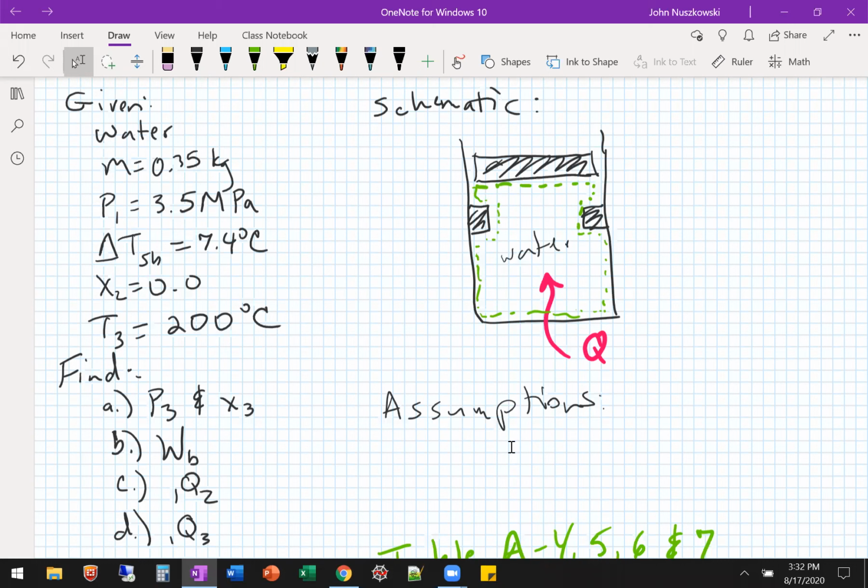So the specific volume? Not from 1 to 2, because the piston's moving down, right? So we're cooling, and the piston moves and hits the stops, state 2, right? So that means the volume will change, and if the mass is constant, then the specific volume changes. Okay. Will the pressure stay the same then? Yeah, the pressure will stay the same.